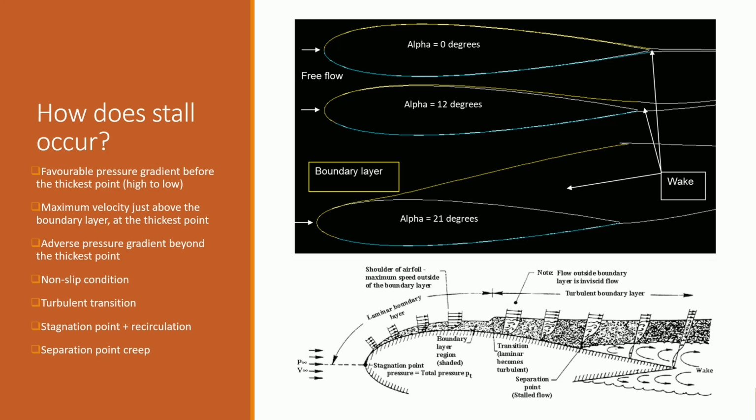The boundary layer grows at this transition point between laminar and turbulent. Beyond the transition point, the flow inside the boundary layer begins to slow down even more, and the surface is having a more prominent effect on the boundary layer.